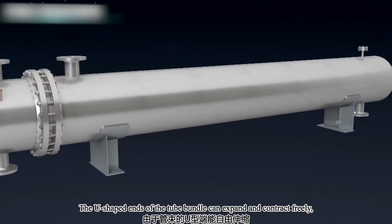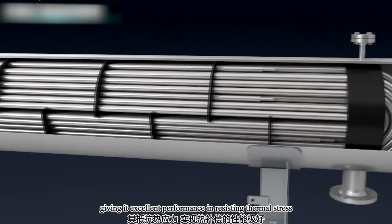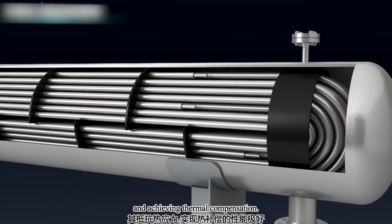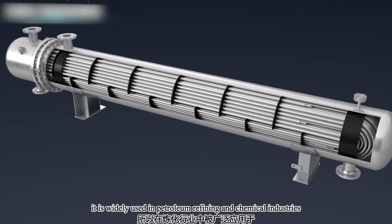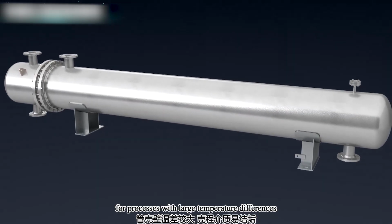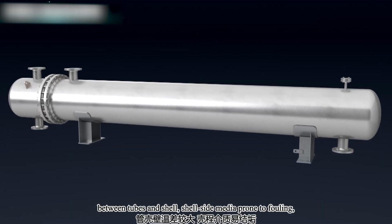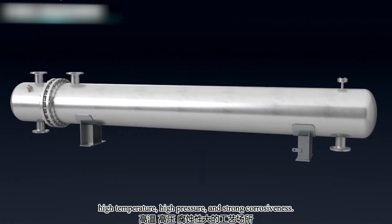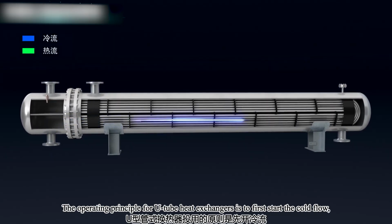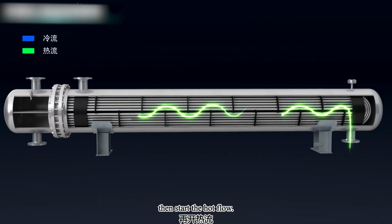The U-shaped ends of the tube bundle can expand and contract freely, giving it excellent performance in resisting thermal stress and achieving thermal compensation. Therefore, it is widely used in petroleum refining and chemical industries. For processes with large temperature differences between tubes and shell side, media prone to fouling, high temperature, high pressure, and strong corrosiveness. The operating principle for U-tube heat exchangers is to first start the cold flow, then start the hot flow.